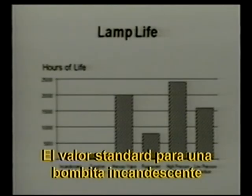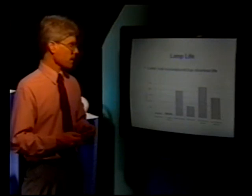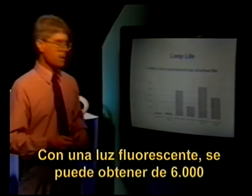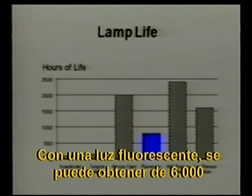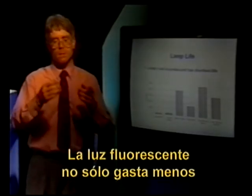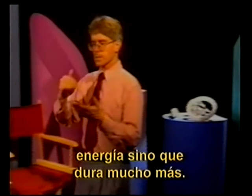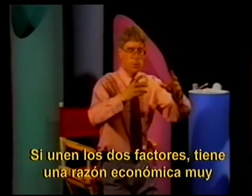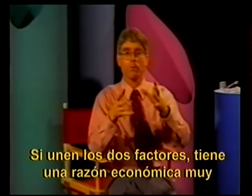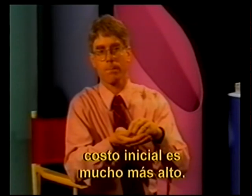Standard value for an incandescent bulb might be as much as 1,000 hours, 800, 1,000, 1,200, something like that. 1,000 hours of operation before it has to be replaced. With a fluorescent light, we might get as much as 6, 7, 8,000, maybe as many as 10,000 hours of operation from that lamp before it has to be replaced. So not only does a fluorescent lamp use less energy when it's operating, but it operates for a much longer period of time. You put those two factors together, and that's a very powerful economic reason for buying what perhaps might be a more expensive light to begin with.